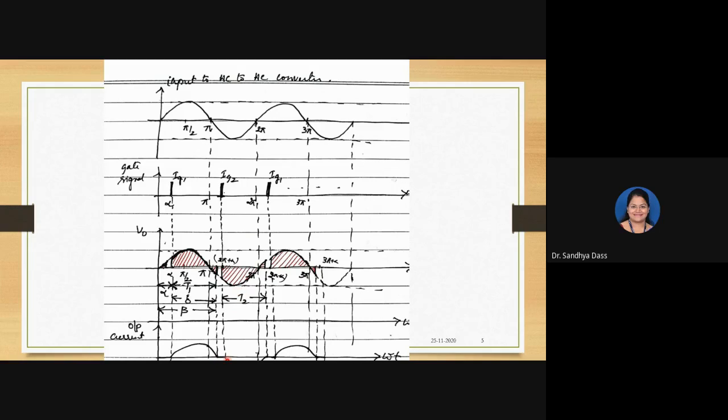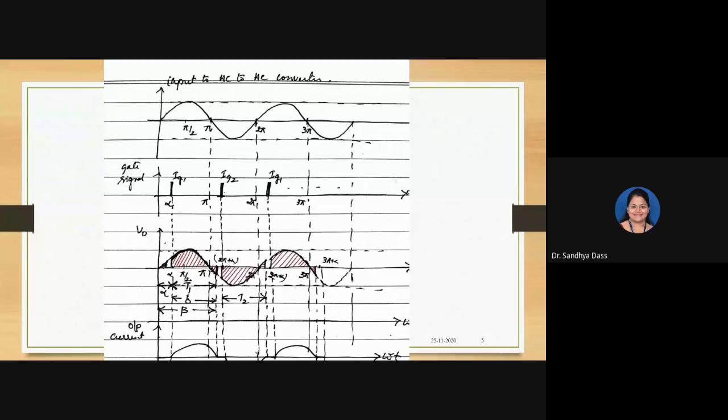Okay. So again, in the negative cycle, as you can see, at this instant, it is because of the inductor. Current is slowly reducing here, dropping to 0. Once it drops to 0, that is when thyristor T2 will stop conducting. Then till you give the next pulse, there is no current because none of the devices are conducting, and this repeats.